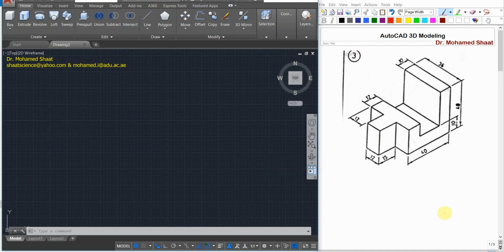Let us start with this simple solid, or shape. If you look at it, definitely according to our definition of the front and side view and so on, it is recommended to take this one as the front view of the shape. This is gonna be the side, the left-hand side, and here we're definitely gonna have the top view.